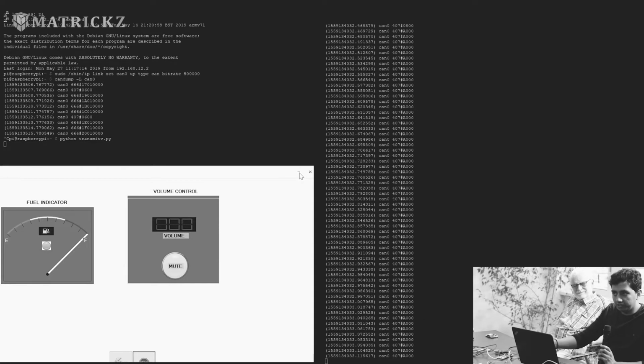This is just one instance that we have simulated, and it was just to show that the CAN bus can be easily hacked into, can be easily hooked onto, and another node can easily send messages. It's all about identifying what each CAN message and each CAN signal does, and duplicating the same with our interceptor ECU.